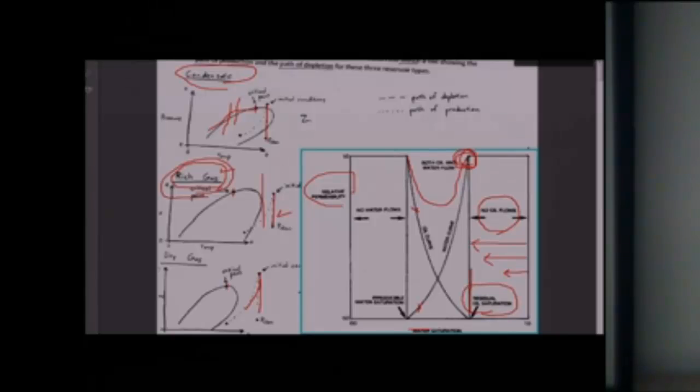But if I know that it's a dew point reservoir and I'm going to have liquid dropout, I could have a drastic situation. I could spend way too much for that reservoir. So not only is this a midstream, upstream decision, it's also a mergers and acquisition decision to know these basic fundamentals of these 3 different kinds of gas reservoirs.